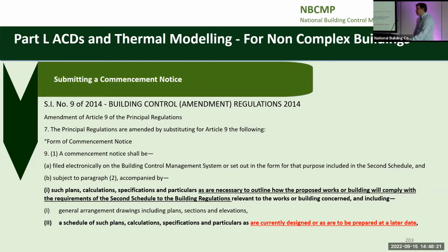So your Part L really should be submitted at design stage. Your ACDs, whether you're using them at that stage or not, should be part of your general arrangement drawings, because your foundation details feed into your thermal modeling and they're part of the thermal model.